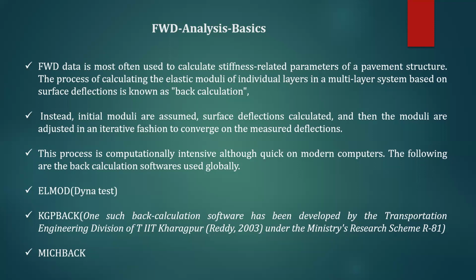So ultimately, whenever the load falls from a certain height, you are going to have some deflections. Here in the falling weight deflectometer analysis, we are going to release that 40 kilonewton. Why 40 kilonewton? Our IRC standard axle load is 80 kilonewton. Half of that is 40 kilonewton. So we want to measure that 40 kilonewton load that is coming on the pavement surface in a dynamic manner, and we want to measure the deflection by means of some transducers or geophones, which we will discuss further.